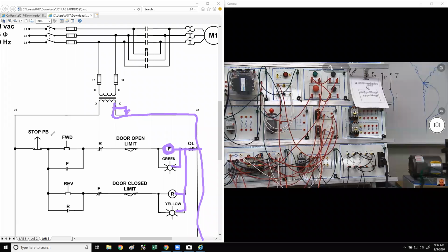So you should know anywhere in this process what should have 120 volts if you put one meter lead here on 2, and one meter lead right here. If the disconnect's on, what should I have here? Should have 120. What should I have here, as it sits? Normally that means you shouldn't read anything.